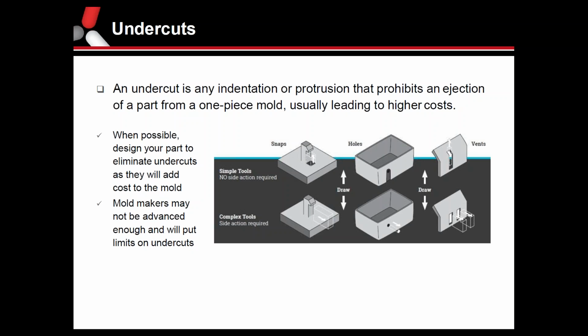Yeah, and I mean, adding undercuts is going to add cost not only to tooling but parts. So just try to keep that in mind. And we'll be happy to review your parts here and give some pointers to see what we can do to help eliminate or minimize them.